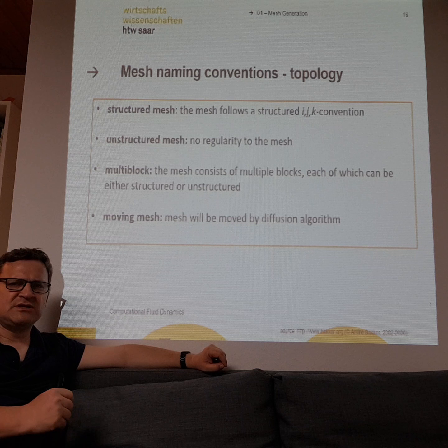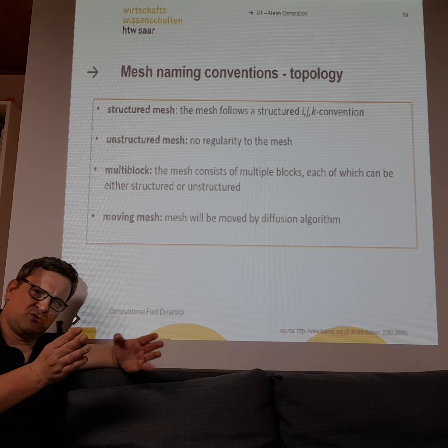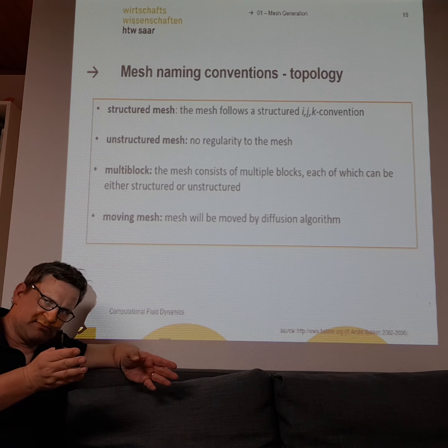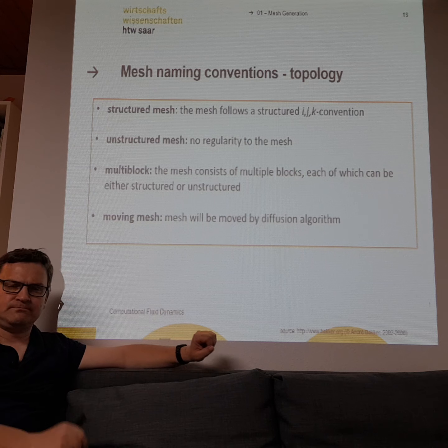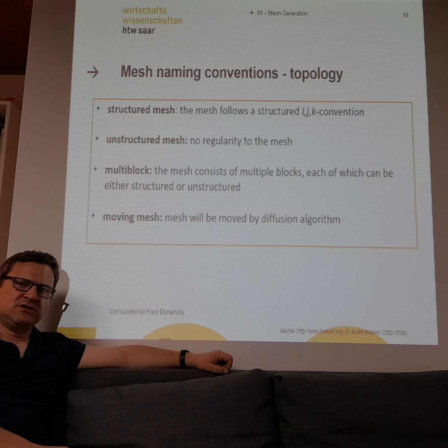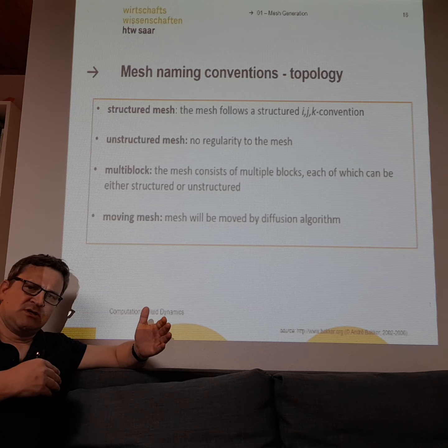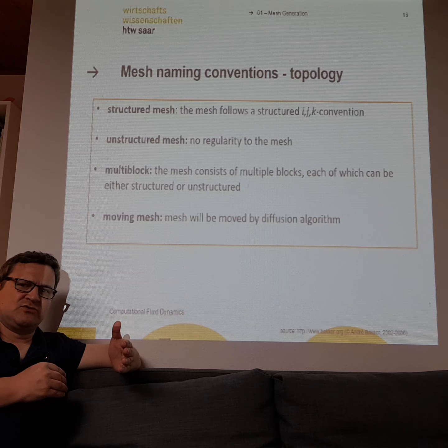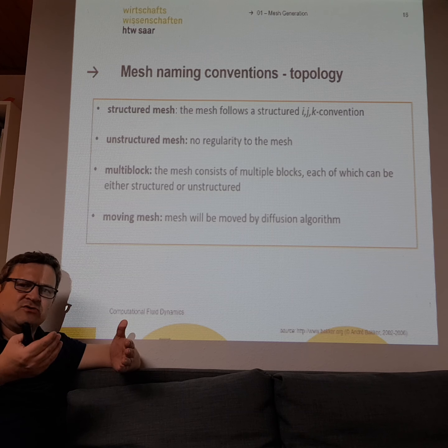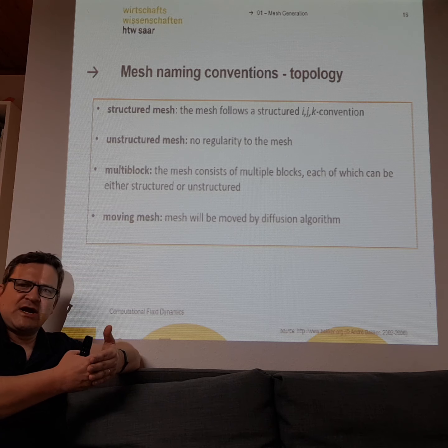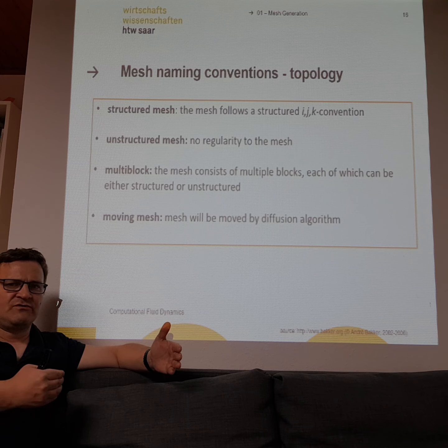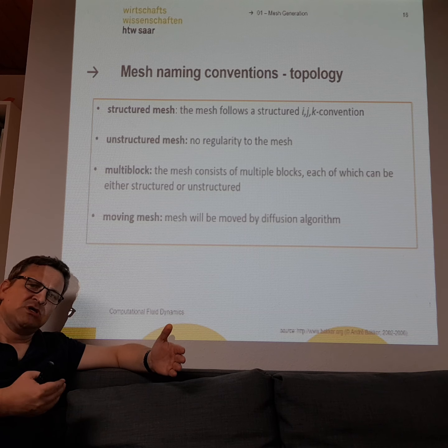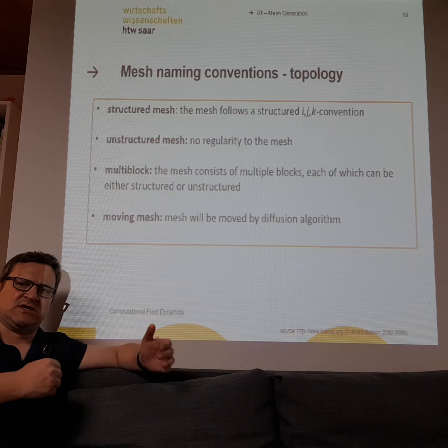For example, cylindrical coordinates, because you can really easily make the coordinate system for this pipe. But what is difficult? Opening and closing of the piston. This is rather tough. Do you want to make the flow simulation for high crank angle numbers, low crank angle numbers, for big volumes, for small volumes? Every result will be wrong. So you need a moving mesh, a moving cylinder simulation.